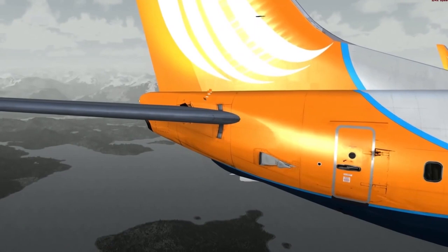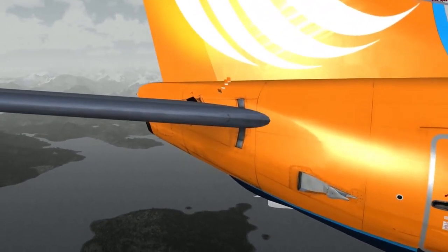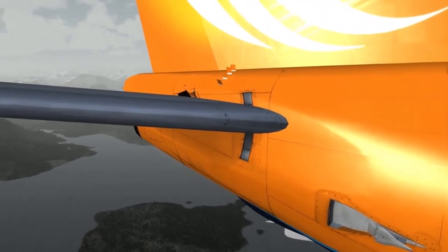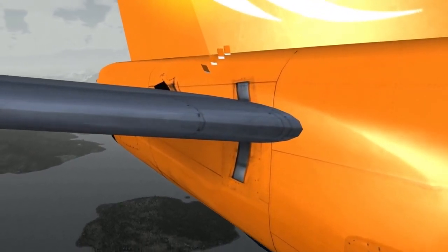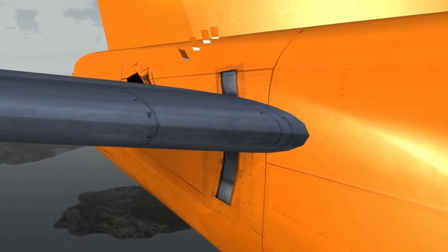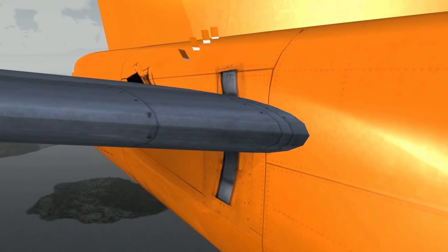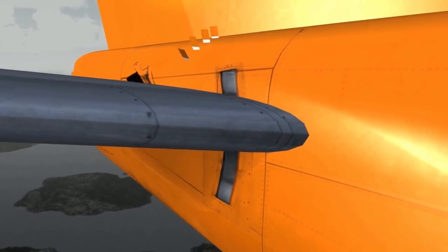The horizontal stabilizer movement lower and higher limits, as well as the neutral position, are marked on the fuselage. The limits are 4.2 degrees of stabilizer leading edge up, 12.9 degrees of stabilizer leading edge down. It's good to keep in mind that when the stabilizer moves up, the aircraft nose moves down, and vice versa.